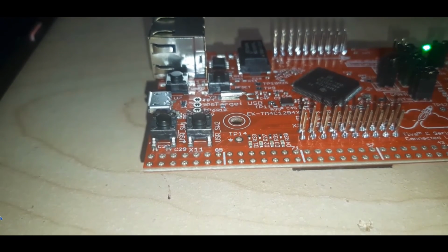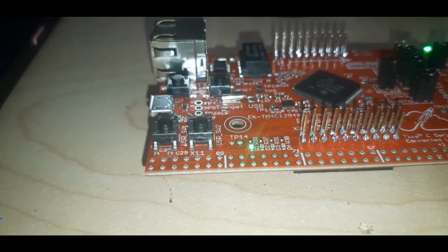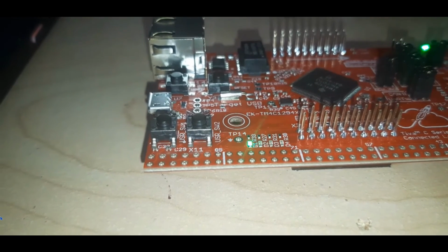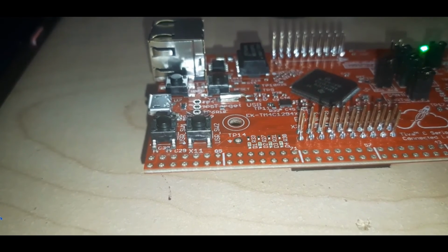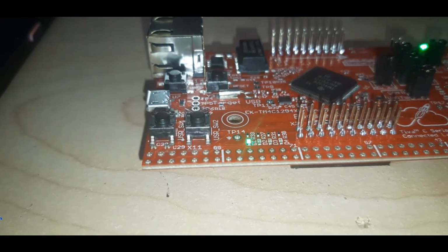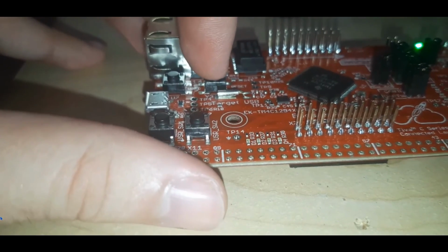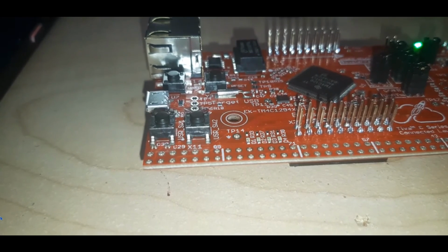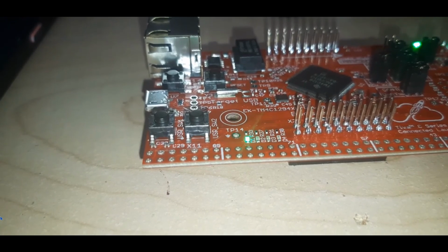double the speed, or make it twice as fast, in our code we would have to see where the delay ms command is and change that number from 1000 to 500, because now we want it to blink at 500 milliseconds. So if we now build and load that onto our board and press the reset button, as you can see here, it turns on at 500 milliseconds and turns off every 500 milliseconds. And yeah, that's pretty much it.